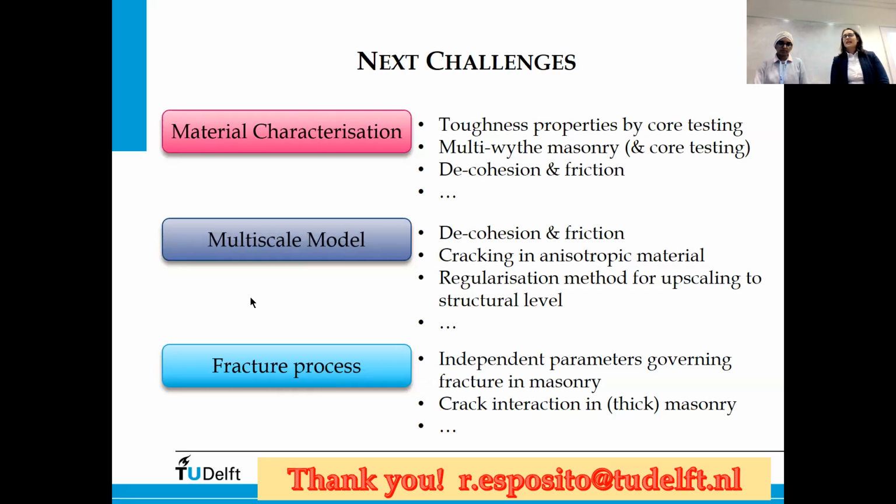We have done all of them in displacement control to try to get post-peak behavior. We also did the orthogonal behavior in compression, the shear, and the out-of-plane bending in the two directions. We also have done some non-standard in-plane bending tests to try to get some properties in that direction.